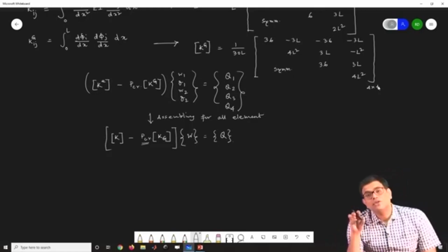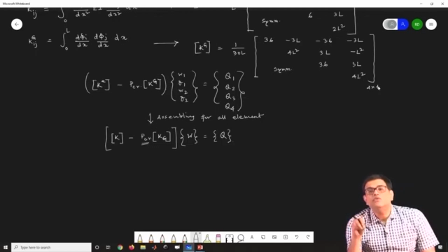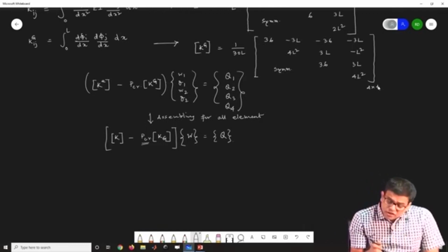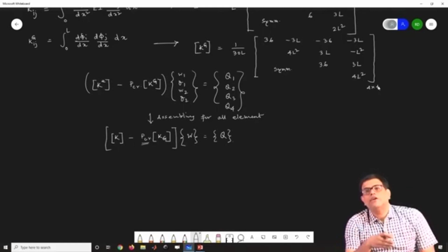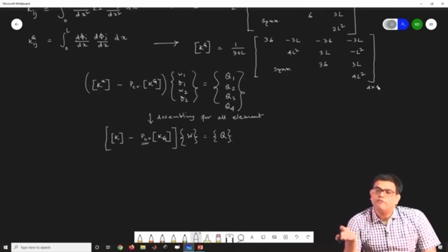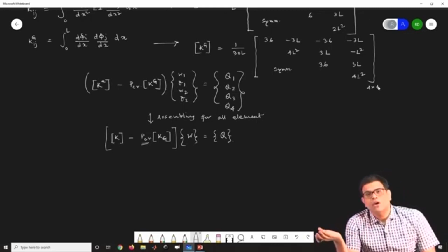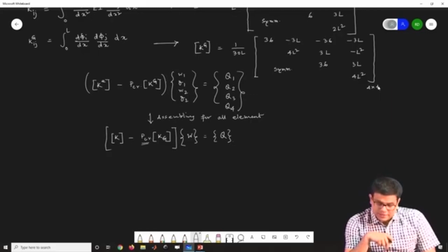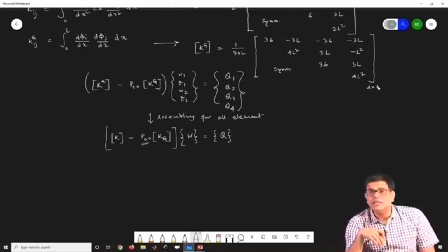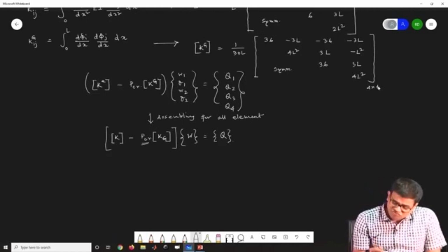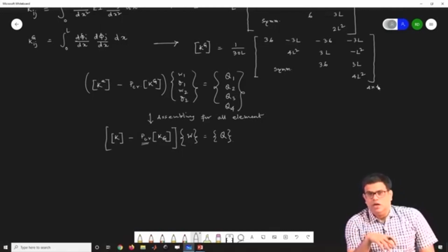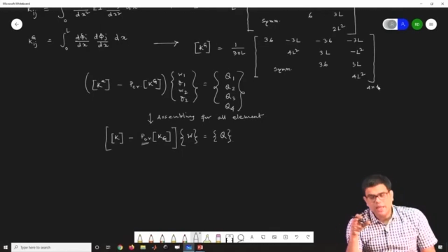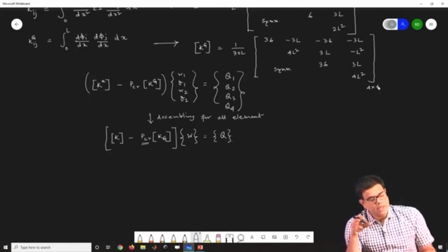So we are interested in the smaller eigenvalue, which will represent my Euler buckling load or the critical buckling load. So that's the overall theory. It is very similar to the frequency domain analysis, or finding out the natural frequency and mode shapes of the beam structure that we discussed last time. So I will just briefly mention one example. You can check it. We'll do some detailed examples probably later.